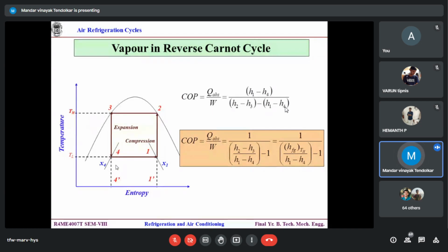With 100% gas, even though it is an ideal gas, the practical difficulty is how you are going to execute the compression and expansion process and the heat rejection and heat absorption process simultaneously. That is the problem. Here, at least you get rid of two processes out of the four: isothermal heat rejection and isothermal heat absorption. You need not worry about the speed because there is phase change, latent heat. When you use the gas, everything becomes sensible heat, sensible heat rejection, sensible heat absorption. So there is a problem. Are you getting it? Yes, sir.